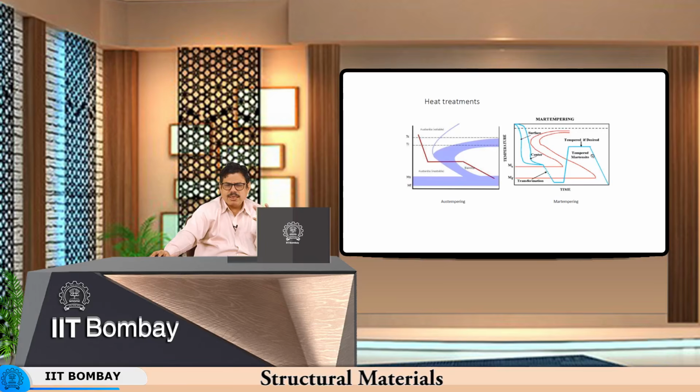So basically it's much lower in carbon, it is much lower in hardness, while the strength due to increased pearlite will go up. So essentially you are retaining the hardness, well, it will make some difference to the hardness, it will lower the hardness a little bit, but then your toughness would increase by a significant amount.